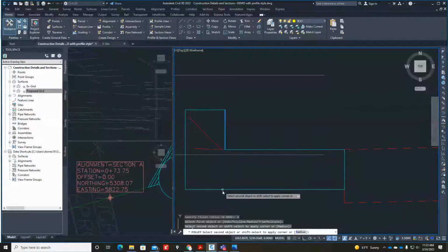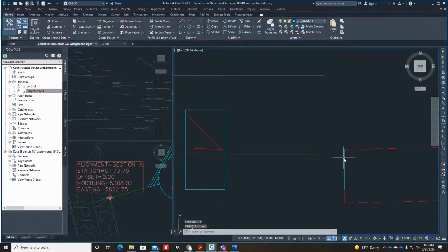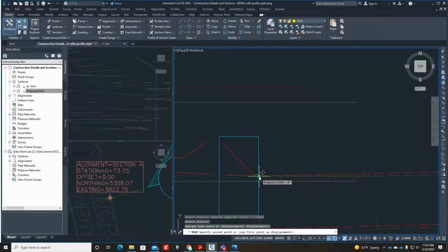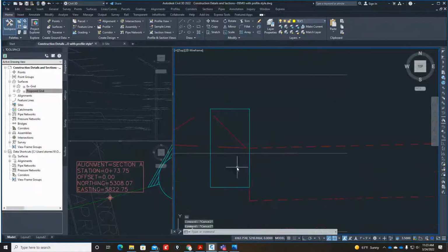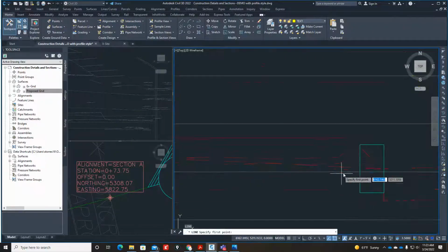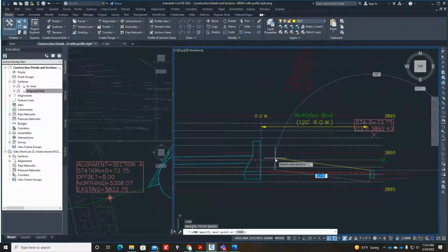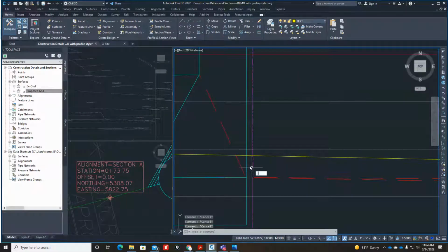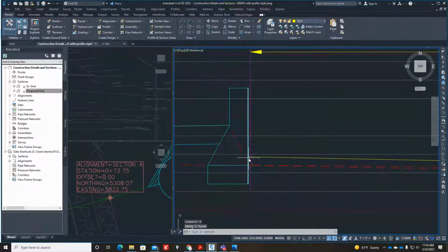So we're going to delete this guy from there to there, erase this one to be more exact once again, and then move this existing pavement from this point perpendicular to there. That's our standard curb existing. And then this is at a 2% sidewalk. I don't know if I showed you guys this trick, but you can draw it at a 2%. It's going to go at -100, comma 2, coming up this way. That way it draws it at 2%, and you can see there's actually a little bit of fill right in here. And then this is where we're going to put in our new sidewalk of 0.33 thickness.